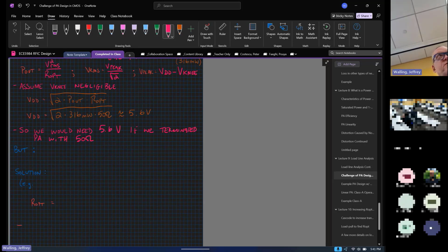All right, what's the supply voltage for your process? The maximum VDD? 0.9. 0.9 volts. All right, 0.9 volts for your process. It's even lower for 12 nanometers or smaller FinFETs.